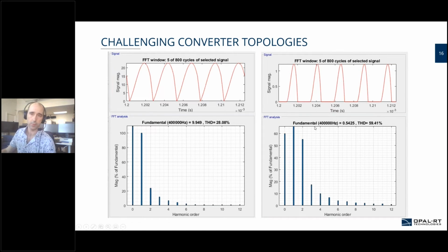So in order to simulate a switching frequency around 200 kilohertz and have all the harmonic content of the rectified signal, you should go for a time step closer to the hundreds of nanoseconds rather than 200 nanoseconds.